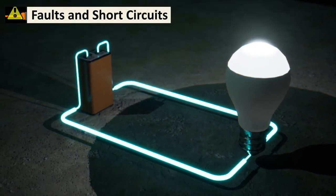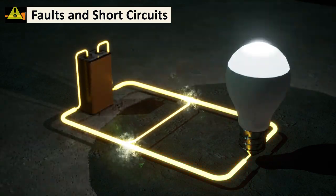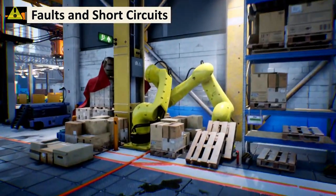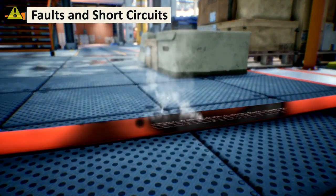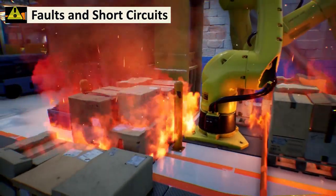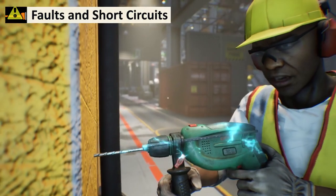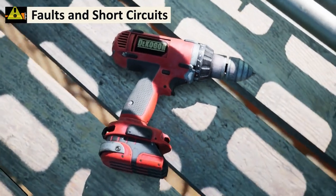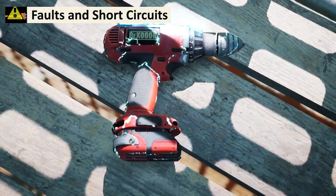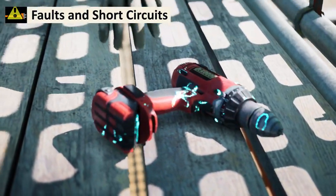When a short circuit occurs, the low resistance allows more energy to flow through the system than intended. This can generate a lot of heat rapidly, which can melt wires, damage electronics, and ignite flammable or explosive materials. A ground fault can energize an unintended part of the equipment. For example, if a wire inside a drill comes loose and contacts the metal housing of the drill, the entire housing could become electrified and shock anyone who touches the drill.